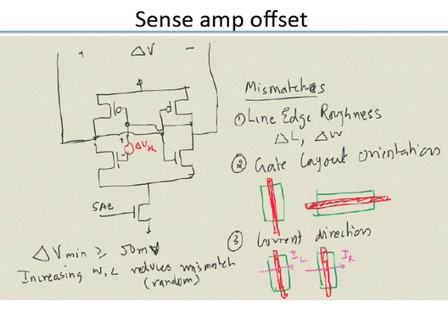So one of them has a larger threshold, say this one has a larger threshold voltage, or this one has a smaller threshold voltage compared to this. If I had shown the polarity opposite, it would have illustrated better. But basically, even though you created this external voltage difference, it is no longer sufficient to create a corresponding current difference, because internally the threshold voltages are still favoring the other transistor.